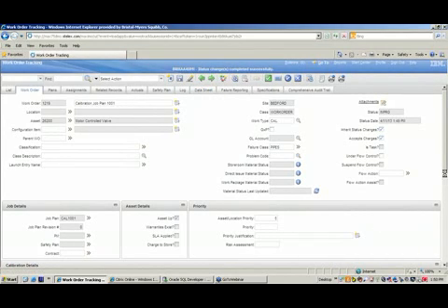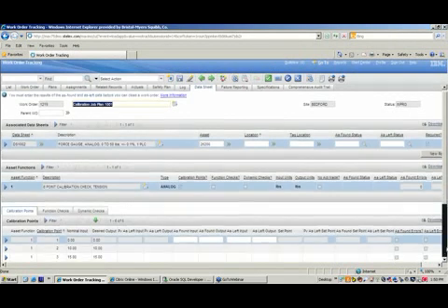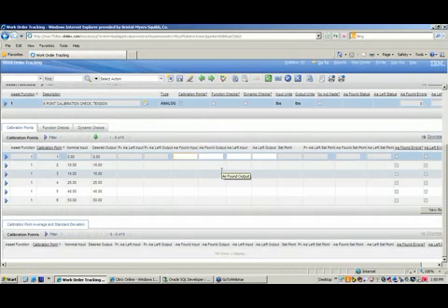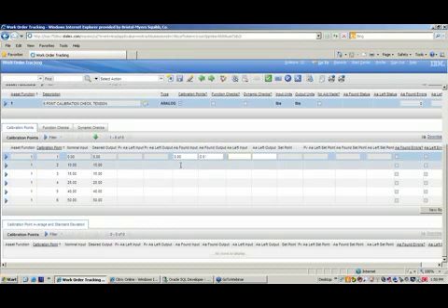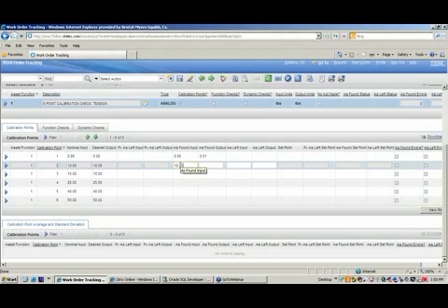Okay, so now under our data sheet section, as we bring up the records, the technician, as he starts going through the values, will now be able to start filling in the as found and as left values, as found input, and then basically if he has some deviation, he can enter it as well. So as the technician goes through, he'll be able to click on each record and enter a value.